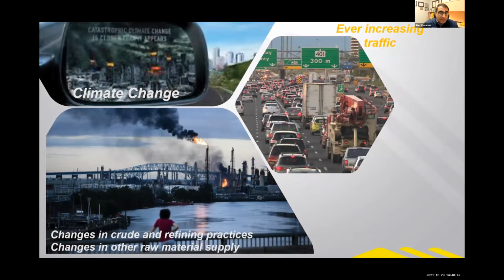As I mentioned, the factors that influence pavement deterioration are not only important at the time of the design. We want to know how the climate is changing, which is one of the major topics these days, the rapid change of climate. We want to understand the traffic, which is the primary point of the stress. That stress is being put on roadways, and as the traffic is changing, the stress is changing. So when we are designing, we have to include a level of factor of safety in the design, but we don't want to over-design, because then the cost would increase and might not enable us to place the pavement.